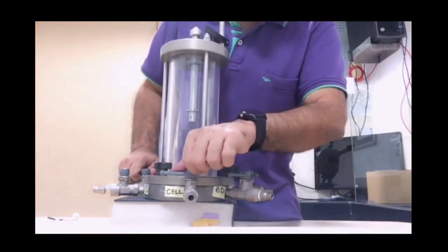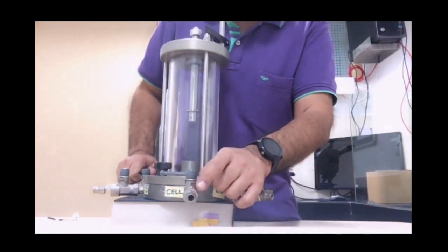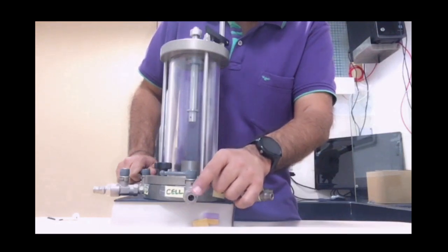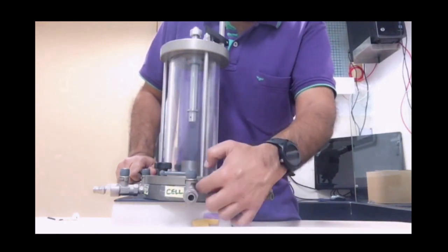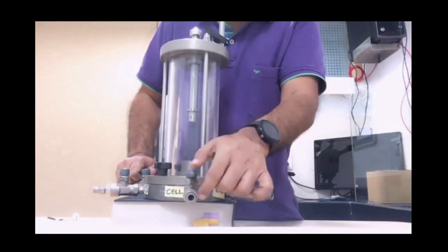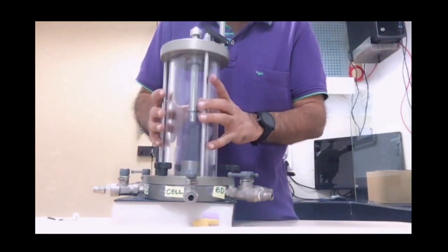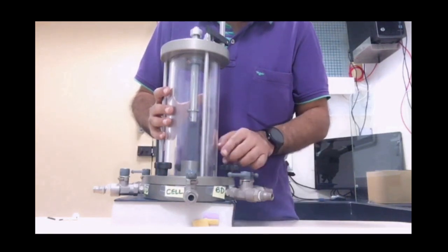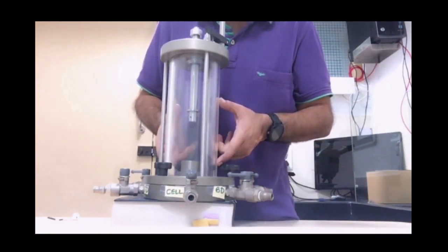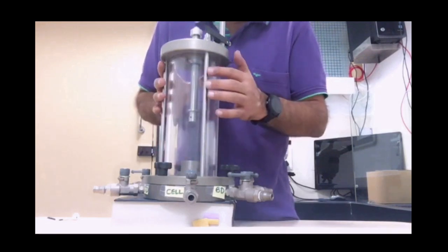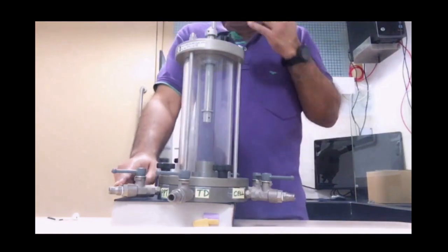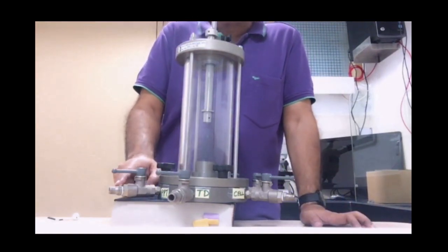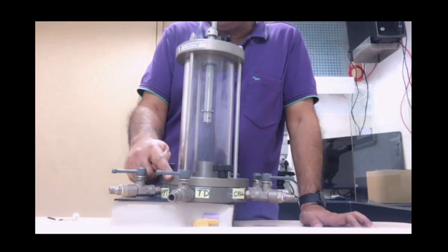What I'll do is increase the cell pressure, which is now 200, to 250. So 250 is waiting to be applied over here. I open this valve, so 250 is now within this chamber. Previously the pore pressure within the chamber was 190, that was the reading given. But now from 190, this reading tells me, let's say, throw in some number, 235.